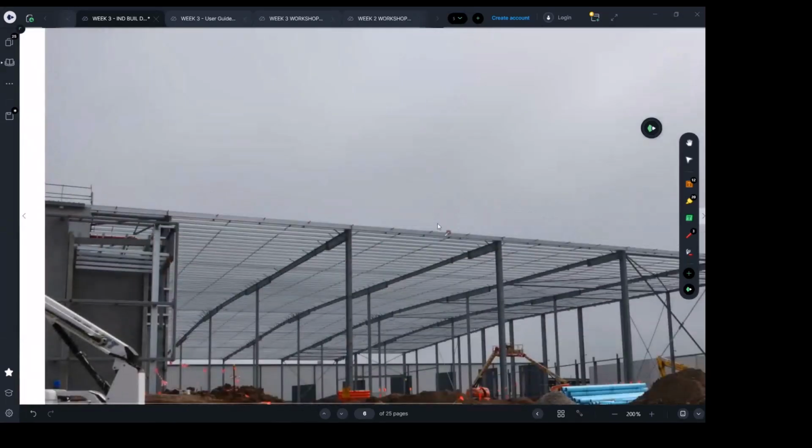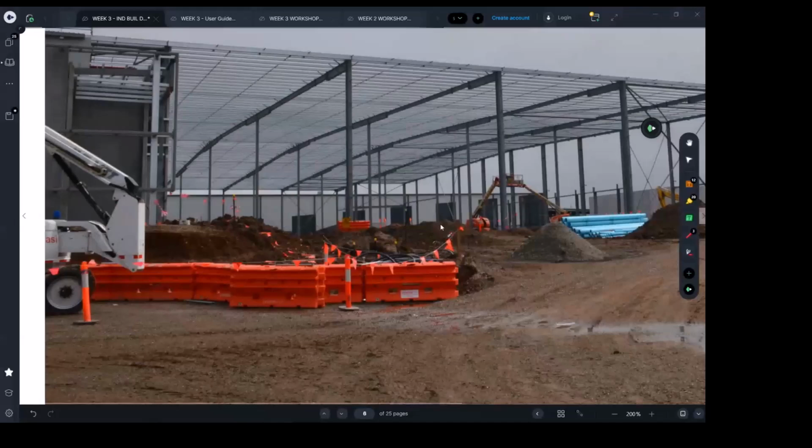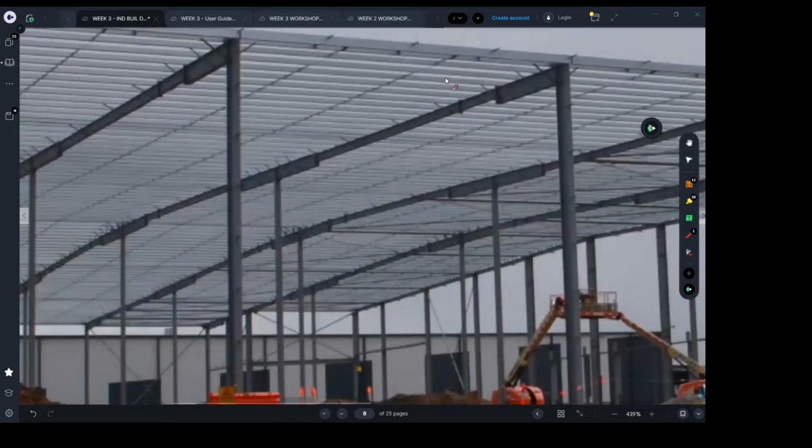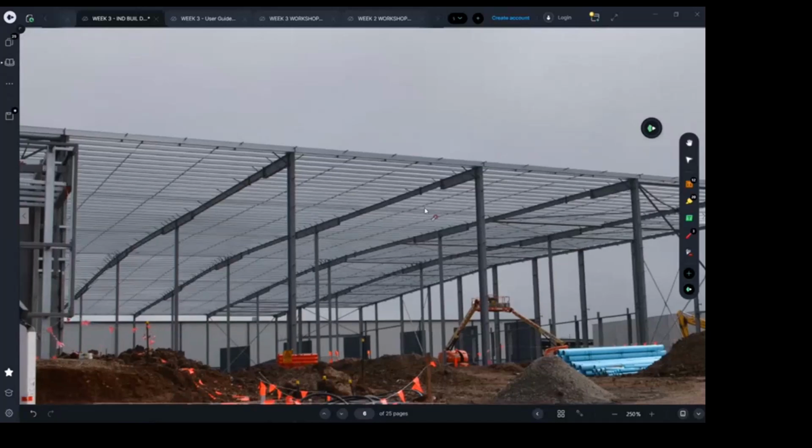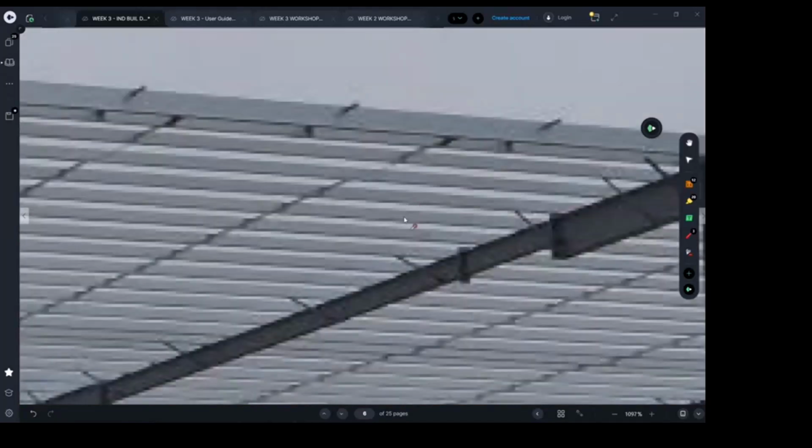No. So the purlins are the ones restraining the rafters through the portal frames. So the answer I was waiting for: the purlins are also restraining the bottom flange of the rafters through the fly brace. That's it.